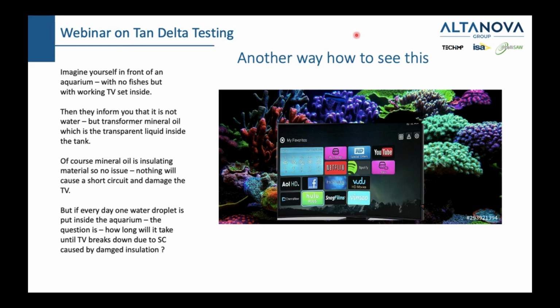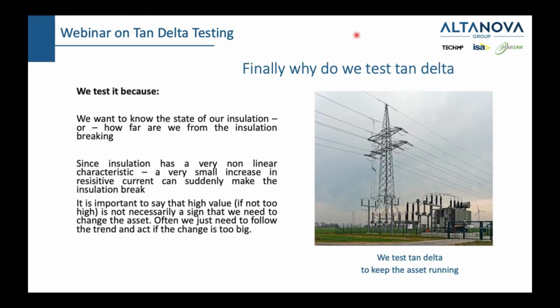You have a transformer which breathes, we'll talk about that later. That transformer attracts water molecules inside, and the water molecules sooner or later can create a short circuit. So what we do here with tan delta, we will measure and tell you when it is high time to get your TV out. And finally, to answer the question why we test tan delta, we test tan delta because